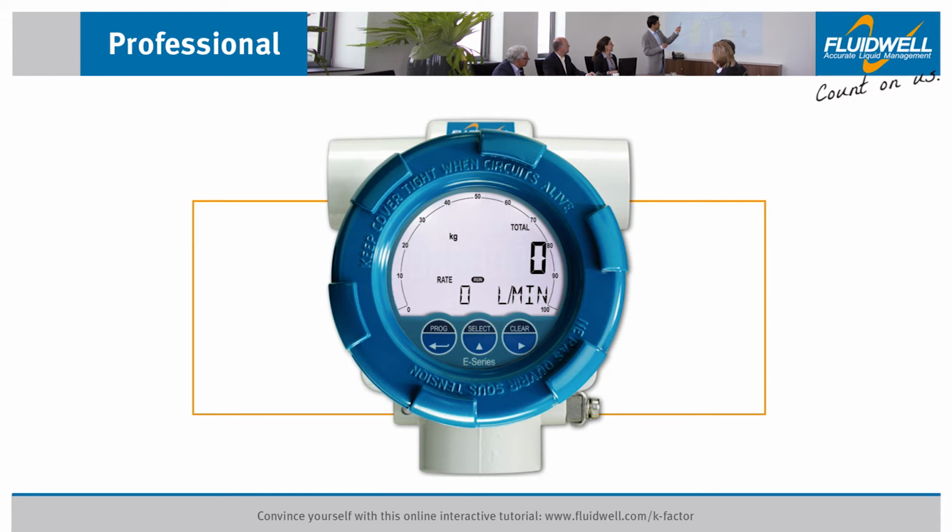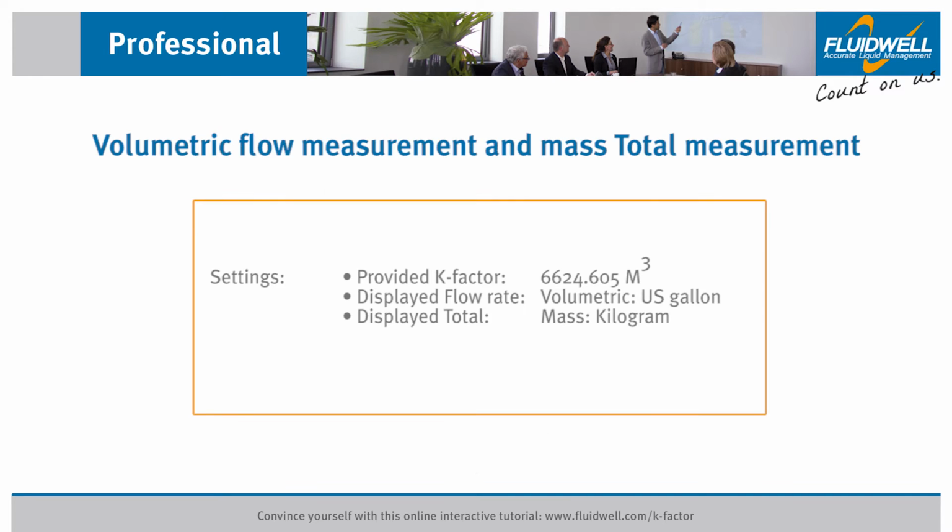The K-factor setting should be configured before installation to ensure correct measurements in any situation. In this tutorial, we will manually set the K-factor for volumetric flow measurement and the K-factor for mass total measurement. This setup is often used in weighing applications with flow meters.